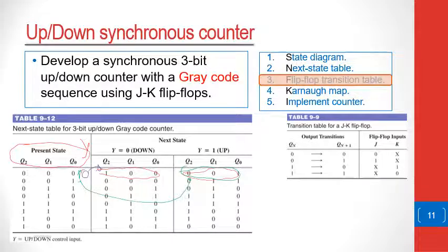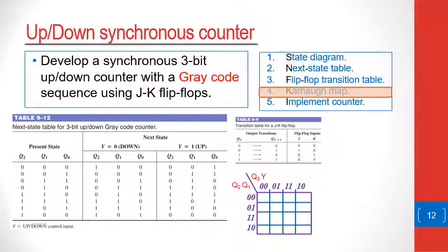And so we are also mindful of the fact that the way the flip-flop works is, if we want to quickly do a summary, we see that the input K here is important when the present state is 1. And the input J is important when the present state is 0. So for the input J, we can ignore this other part. Here we can only consider the input K. So let's see how we can use that.